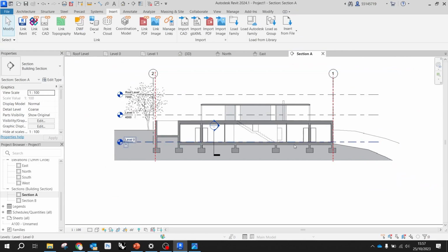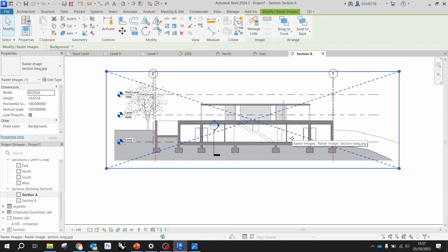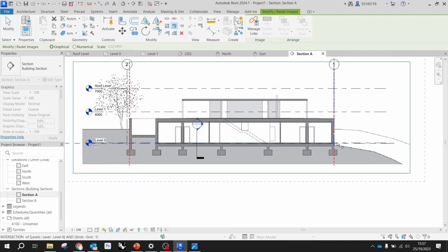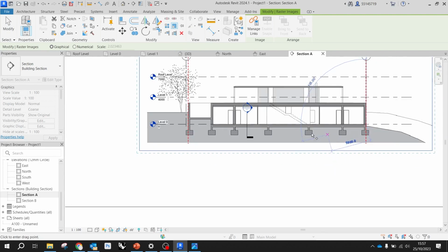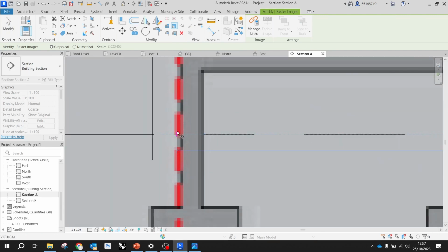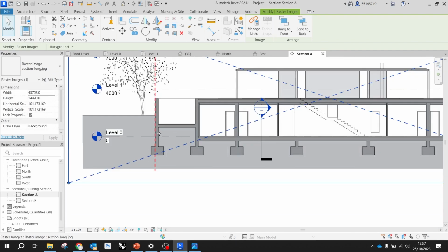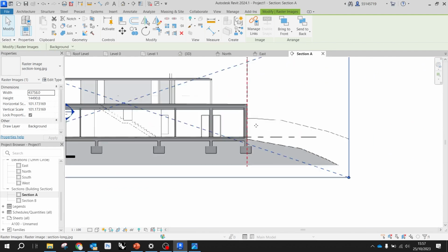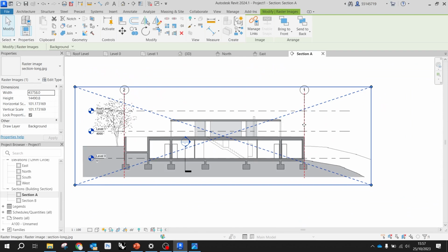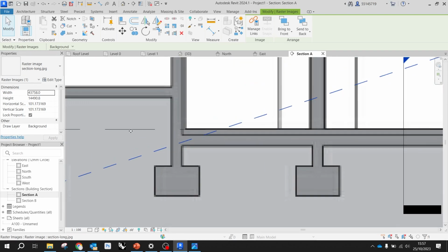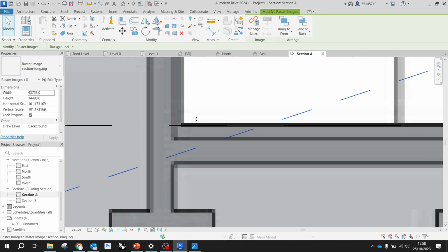And after we've done that, now we can finally scale this. So yeah, give me 1 second. Just gonna do this for everyone. So select the image back again from where the two grids intersect to the second red grid, and just extend it once again to where our grid intersects. So now grid 1, grid 2 are perfectly aligned to red grid, and level 0 is level to finish